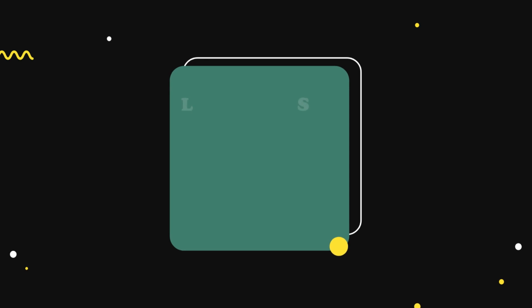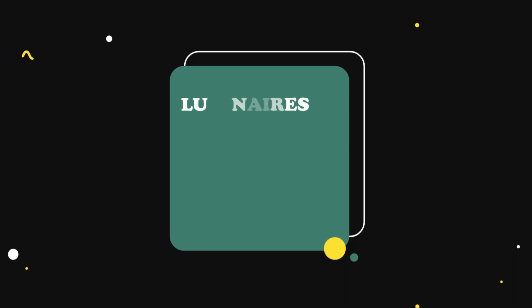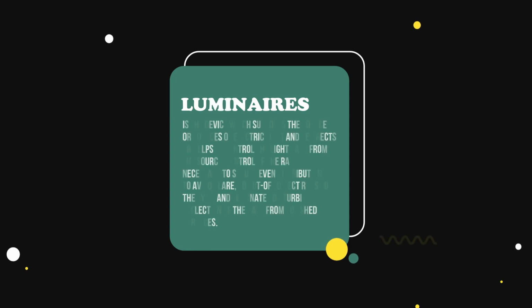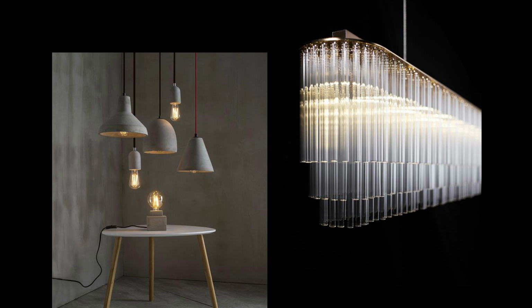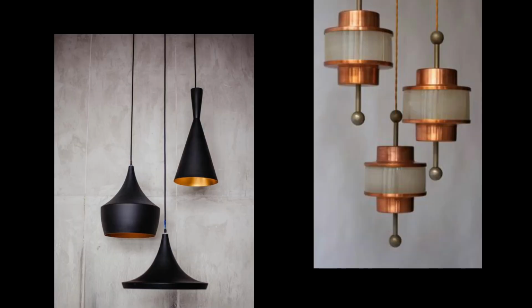Luminaires, or lighting fixtures, are devices which support the source or sources of electric light and help to control the light rays from the source. Controlling the rays is necessary to secure even distribution, to avoid glare, to prevent direct rays to the eye, and to eliminate disturbing reflection of the rays from polished surfaces. The following are examples of luminaires: ceiling-mounted downlights, spotlights, pendants, wall lights, task and table lights, floor lights, fluorescent fittings, oddities, and exterior lights.